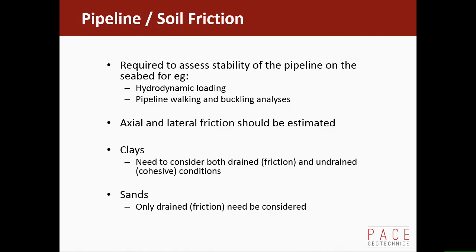Now we've calculated the depth of embedment. What we're actually going to use in design is probably the pipe soil friction. And that's required for calculating hydrodynamic load and the stability of the pipeline actually on the seabed, and then it will go into any walking or buckling analyses that we might do.